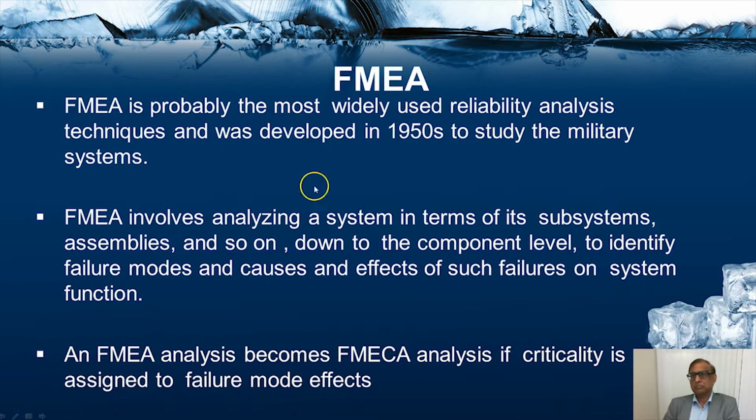So FMECA is the most widely used reliability analysis technique and was developed in the 1950s to study military systems. As you know, the history of reliability started in the 1950s, and FMEA was one of the methods. Failure mode effect analysis involves analyzing a system in terms of subsystems, assemblies, and so on, down to the component level.